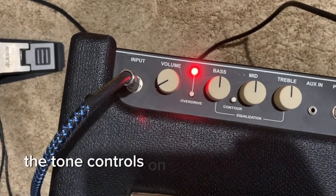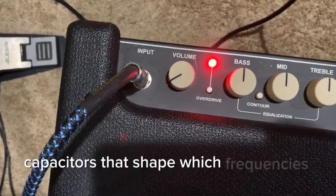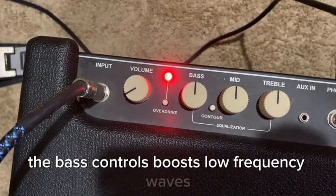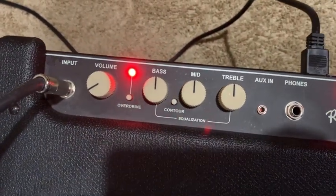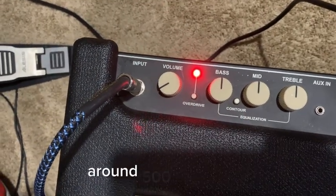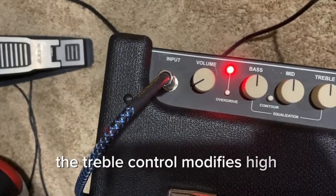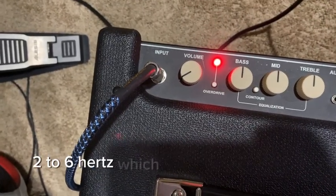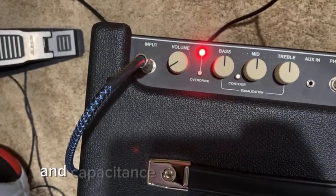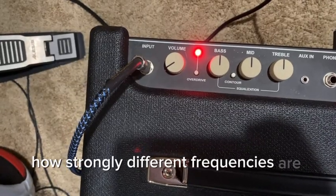The tone controls on an amp are actually RC filters, resistors and capacitors that shape which frequencies pass through. The bass control boosts low-frequency waves around 80 to 200 Hz. The mid-range control affects the frequencies where the guitar's character lives, around 500 to 1500 Hz. The treble control modifies high frequencies, 2 to 6 kHz, which add brightness and clarity. By changing resistance and capacitance values in the circuit, the amp alters how strongly different frequencies are amplified.